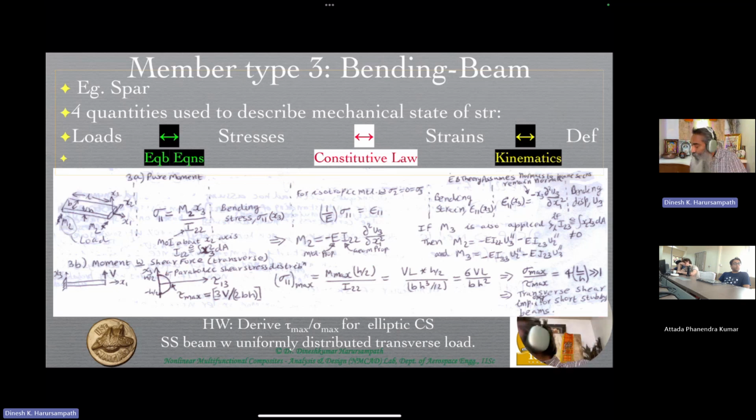But in the actual aircraft, this is not a simple beam problem, we will have a Reynolds number which is not essentially infinity. Even if it is large, you will have a finite value, and therefore there will be some shear stresses, which may be large or small compared to the inertial stresses, which is what the ratio that the Reynolds number actually determines. But for any finite Reynolds number, you're going to have a shear stress because of the viscous flow as well. You don't have an inviscid flow, but a viscous flow.